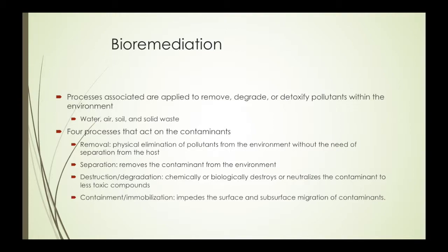Four processes act on the contaminants: removal, which is the physical elimination of pollutants from the environment without the need of separation from the host; separation, which removes the contaminant from the environment; destruction or degradation, which chemically or biologically destroys or neutralizes the contaminant to less toxic compounds; and containment or immobilization, which impedes the surface and subsurface migration of contaminants.